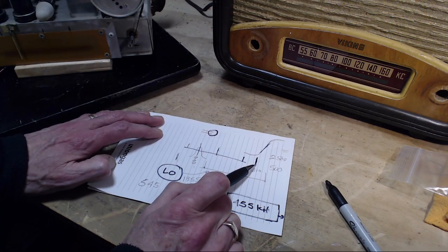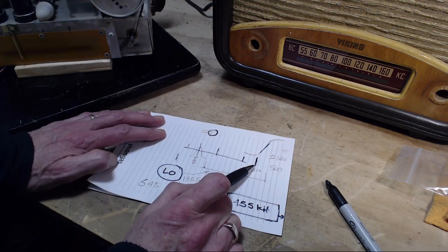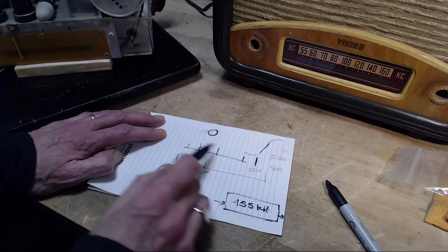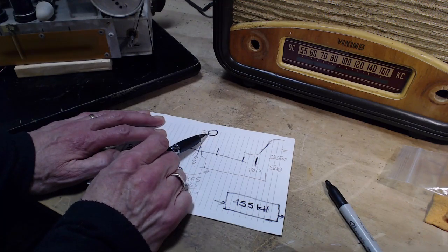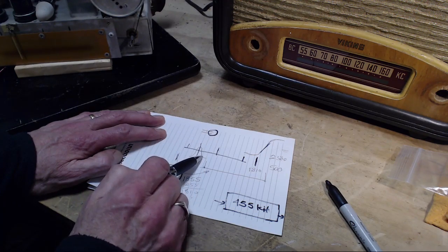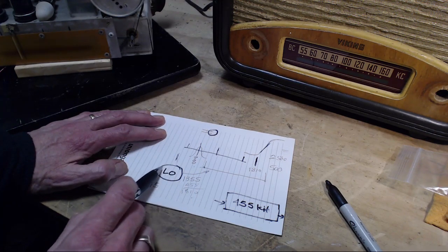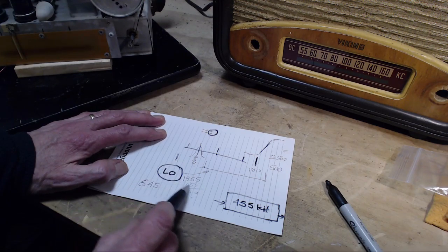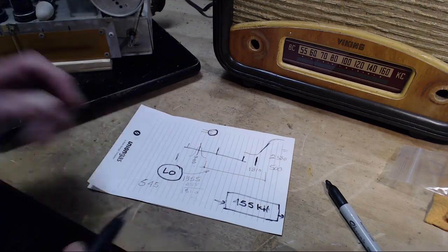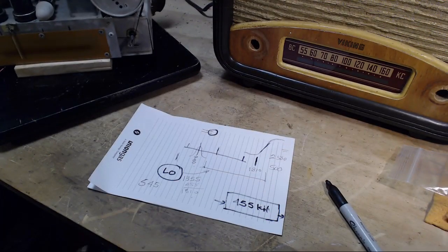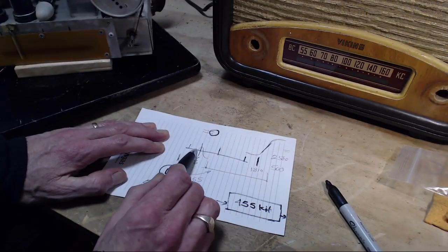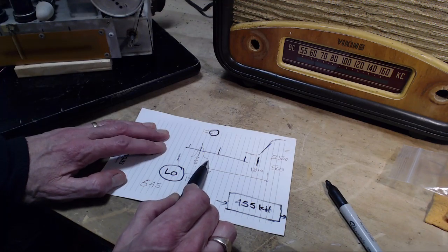Depends on the radio. Now, a lot of radios, and all radios really, should have something ahead of this mixer tube to reduce the amount of stuff getting to it, to focus the radio on this. This signal is going to come out nice and clean. This is an internal local oscillator. It's just nice and clean. The less of everything else and the more of the target frequency you can get into the front of your radio, the better off you are.